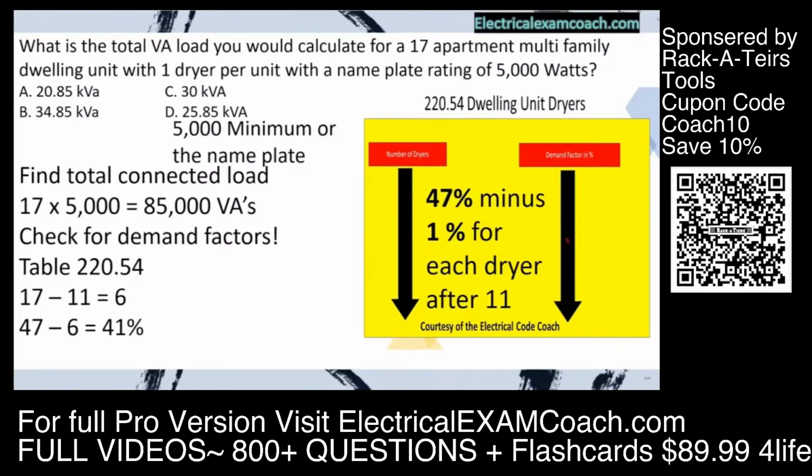Now, all we have to do is multiply. We take our original load, multiplied by 0.41, and that gives us a new reduced load of 34,850 VAs, and we're going to select B. Great job.